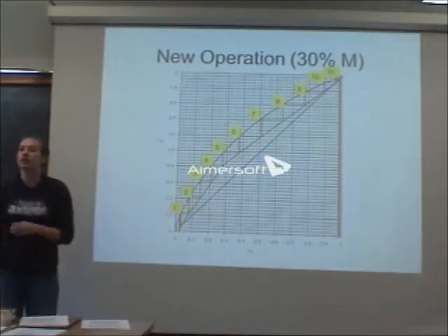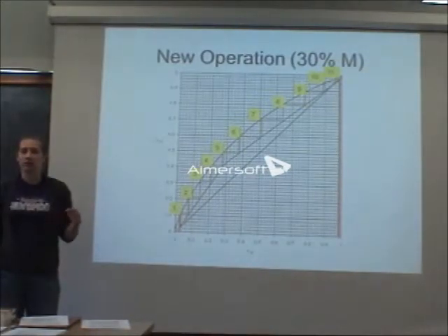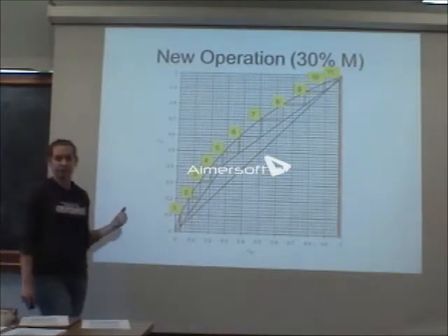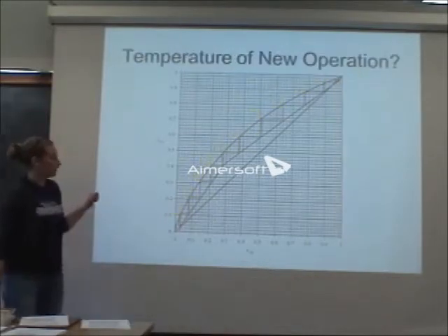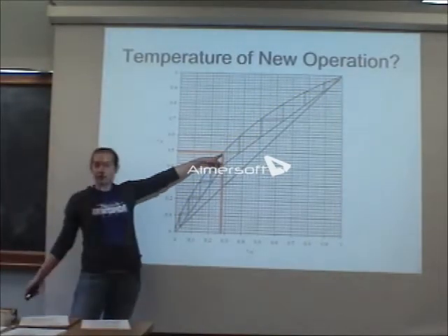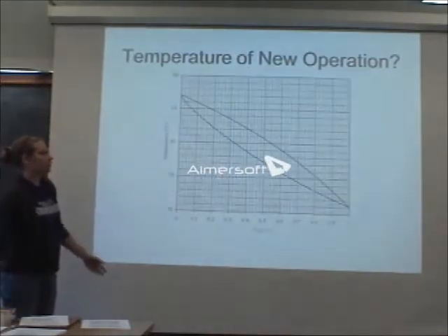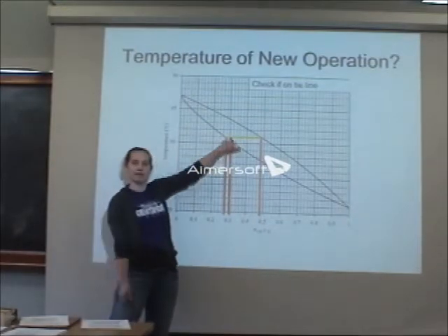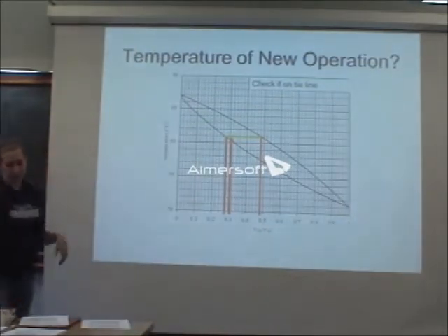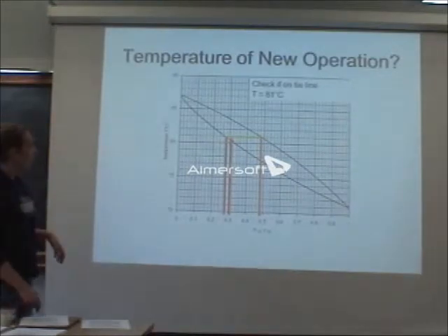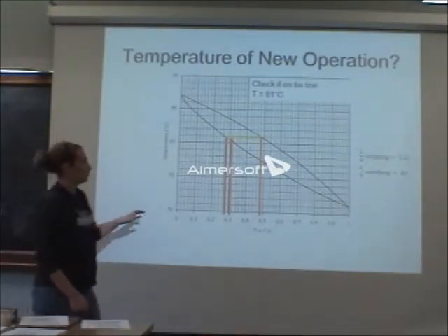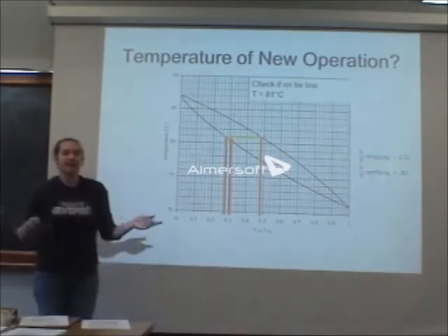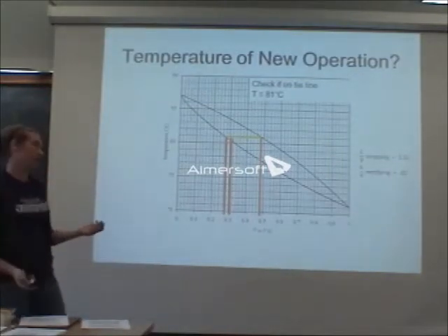So how do I find the new temperature of my cooler? Same way as before? Yeah, Brittany? Okay, you take the feed stage and then use the temperature composition graph to figure out the temperature of the coolant. Yeah, so I grab those off of my equilibrium graph again. My new feed is this. I can plot that on there. And as expected, 0.3 falls within my range. So that's good. You know that's working. All right. Also, I can check my LV stripping and my LV rectifying in the same way, just get the slopes of those. That's going to tell you your two reflux ratios.